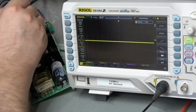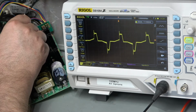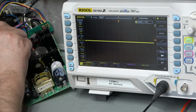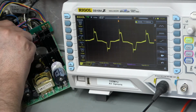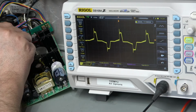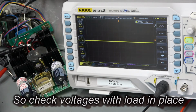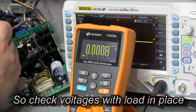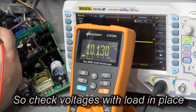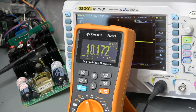Let's have a look at the higher voltages. There's our higher voltage, so everything is switching absolutely fine coming up the front end of this circuit. I've got no concerns about that. So all of that circuit right the way through there appears to be working. Oh, 10.1 volts minus 10. Excellent. I'm going to increase this to 200 milliamps.